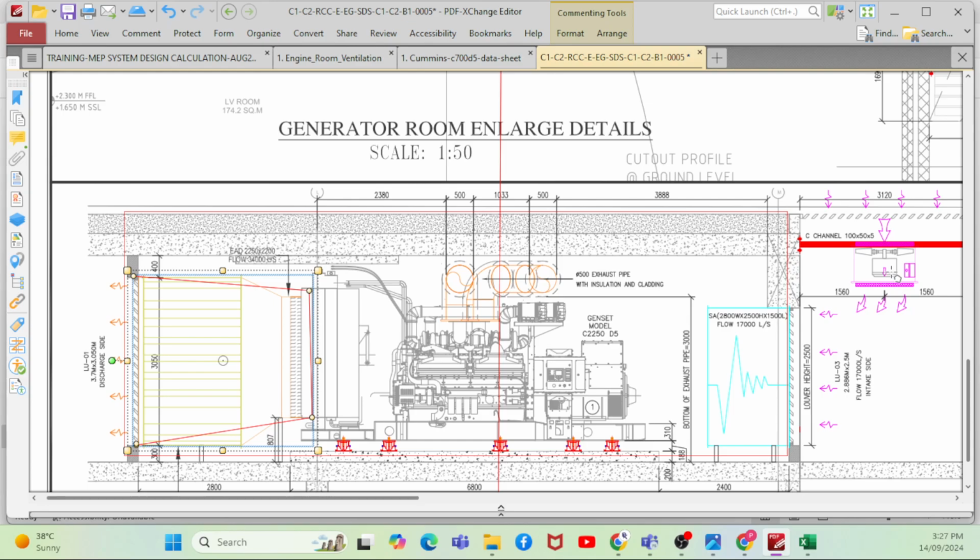But this is where my doubt starts, Pranay. For example, you have a supply side where you basically have an attenuator, your duct piece, and everything. Can you tell me how much you've considered for the attenuator, as a rule of thumb, 40 or no? No, just an assumption, 25 pascal. Okay, let's go with the assumption. For the louver, you have considered 25. Ductwork, we consider like 10 or 20 pascals. So 25 plus 10, that's 35. 35 plus the attenuator, maybe another 30 pascals. Then that means 95 pascals just on the supply side.